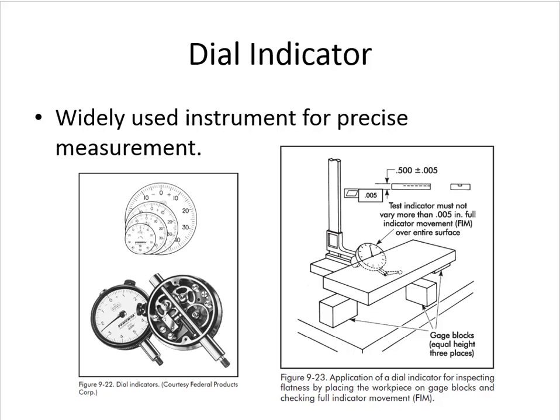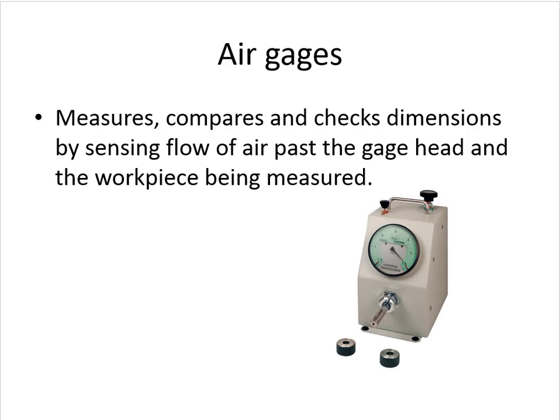You slide that height gauge over the granite, and the stylus on the dial indicator will measure the surface of the part, and what you're looking for is movement of the indicator. They come in different sizes and different increments. A tenth gauge is more precise than a thousandth gauge.